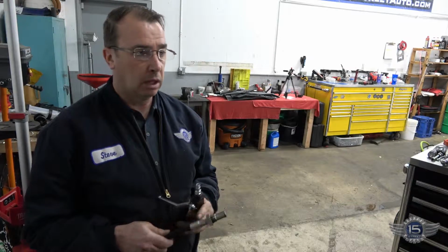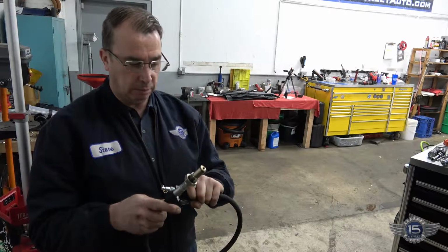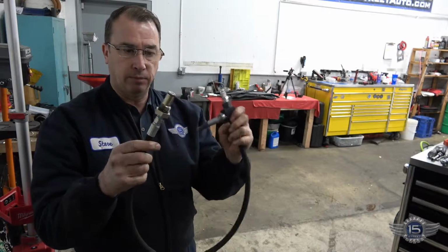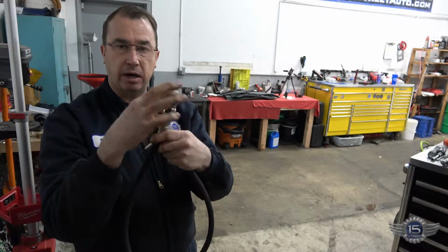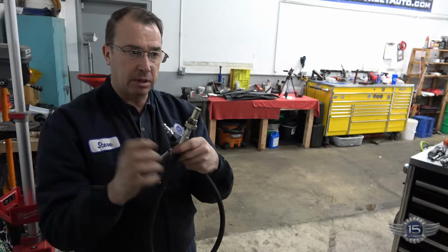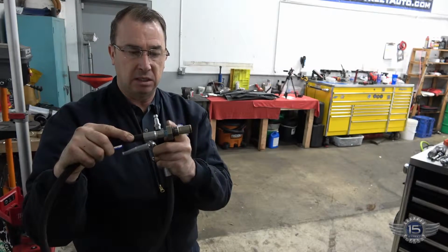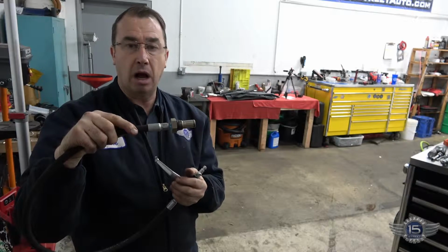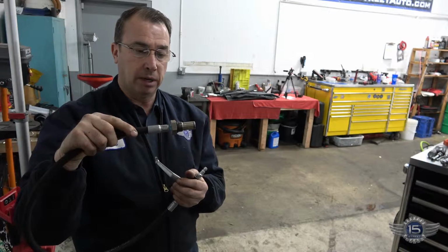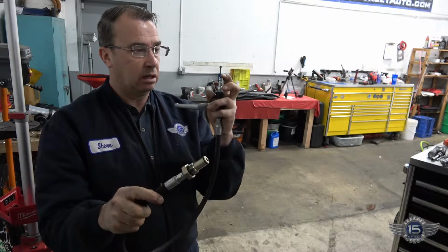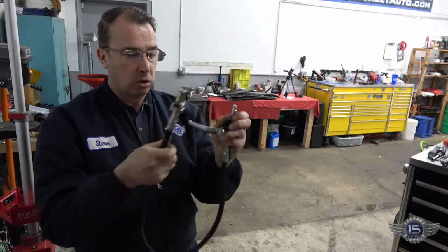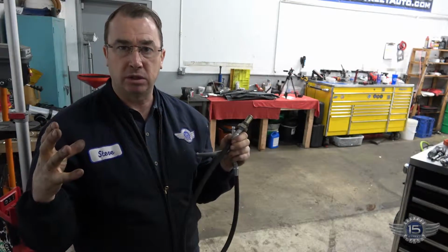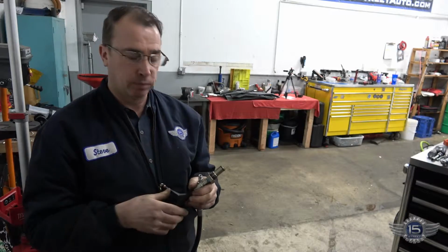So what we do, a little quick test, it's not quick, but it's better than tearing the engine apart, is we have this little gadget here. This goes into the exact area of the IPR. You take the IPR out and stick this in; the shape of it is exactly the same as the IPR. Basically this is a block off for the IPR. But once it's in there, you can introduce shop air to this fitting, open the valve here, and it will put shop air into the entire high pressure oil system. So if there's any leaks, you'll hear them.